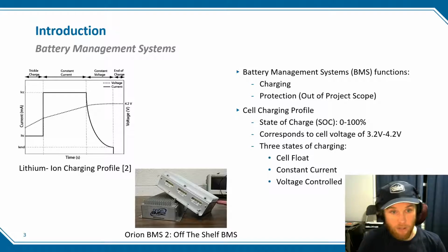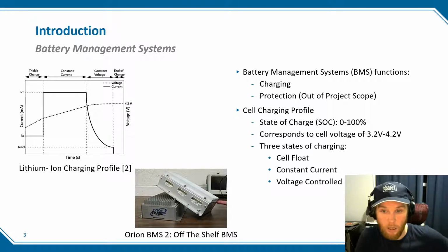And then finally, there's the voltage controlled charging phase, where the cell is gently charged from 80% to 100% SOC. So that's usually from about your 80% to your 100% point of state of charge.